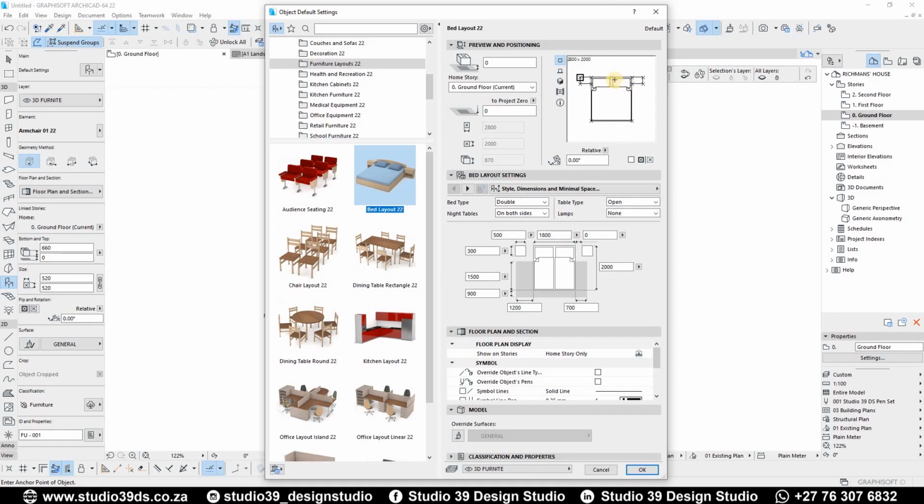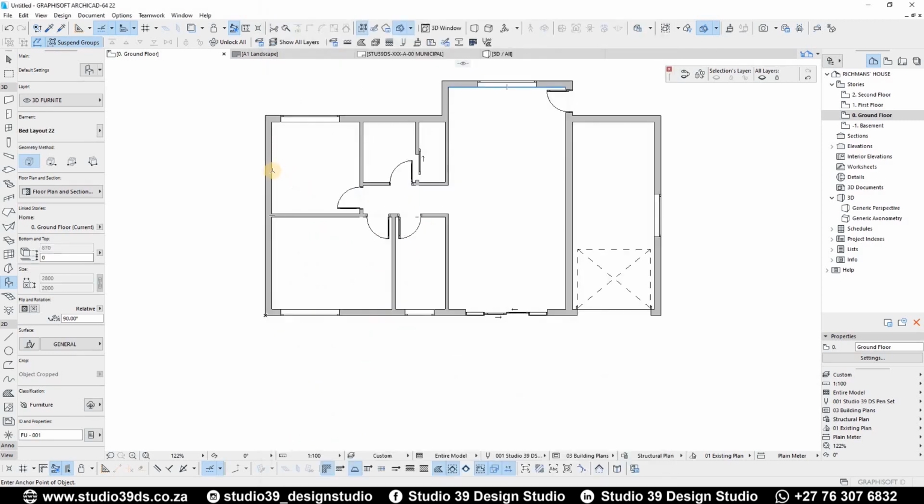So I want my anchor point to be that right there, and then I can also go ahead and flip it like this. As you can see, where my mouse is moving, it's indicating an arrow, which means that you can rotate it from the point. From any point where you see it, it just shows you how you can rotate an object before you place it, if that's something that you want to do. So when I place it, I just go across this wall and just place it like that, and also across this wall I'm just gonna place it like that.